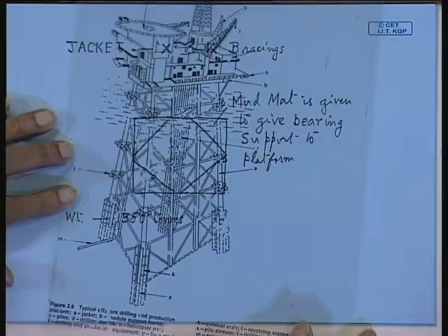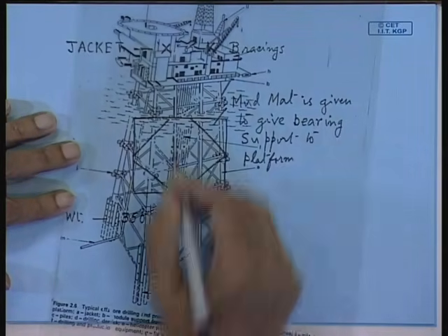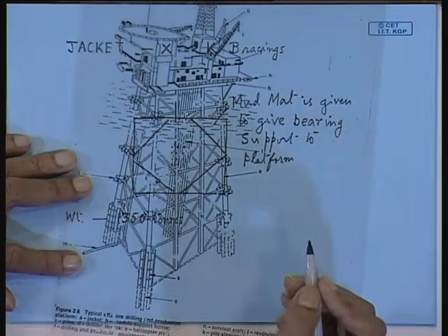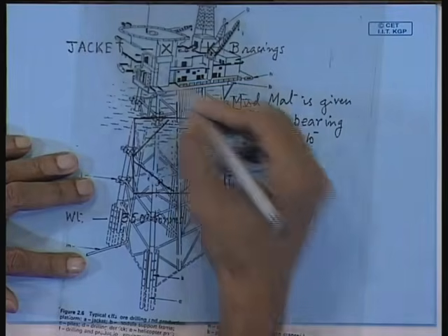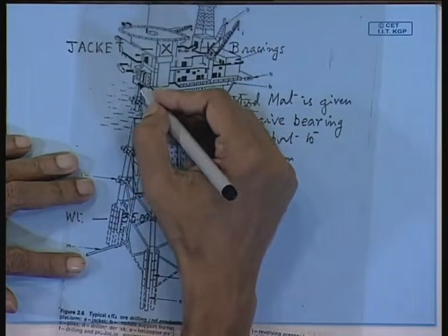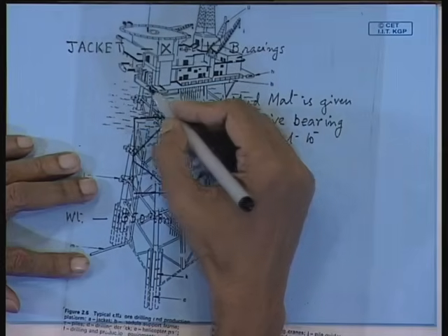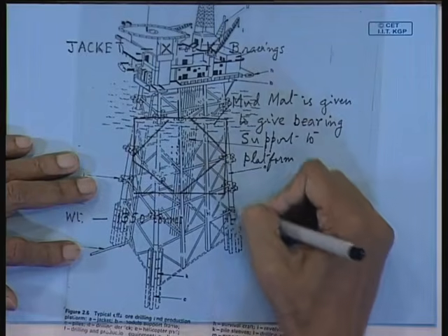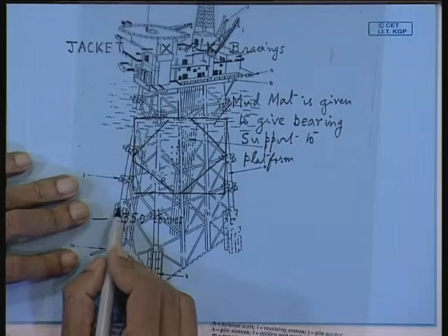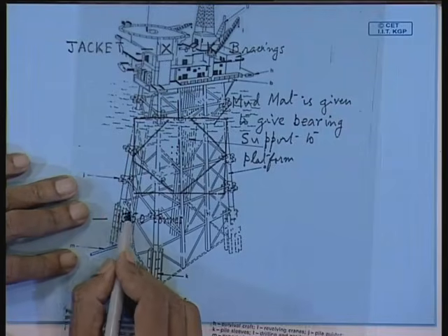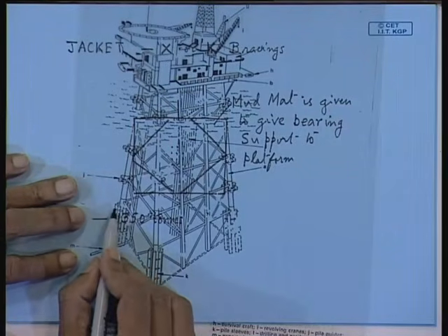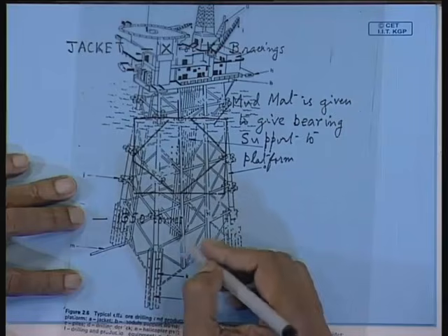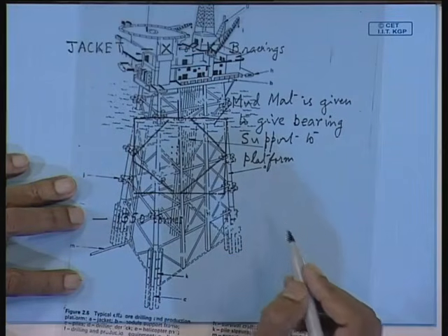So, what you have to do is, first you have to build the truss, and literally you have to pin this down to the seabed by means of piles. Now, as I see here, I think this jacket does not have the long piles which are driven through the columns. Sometimes they also drive piles through these columns. So, those are called the main piles, and the other you can find around the circumference, there are the shorter piles, these are called skirt piles, and here you can see there are as many as 8 around, I think here it is less, around each of the main columns.